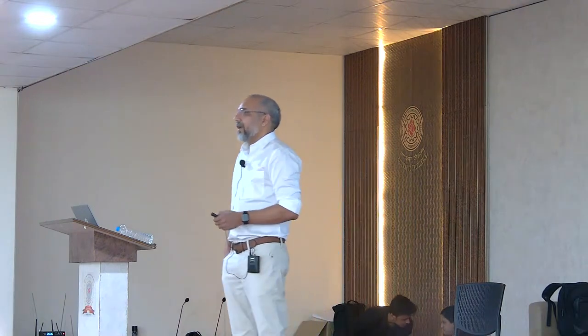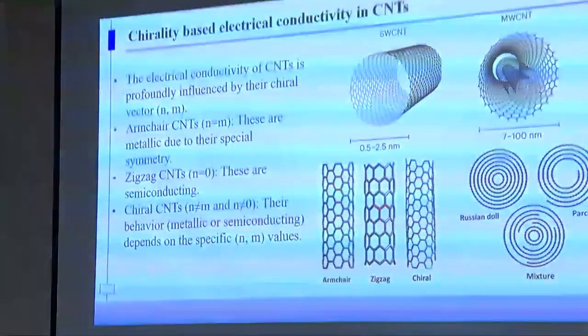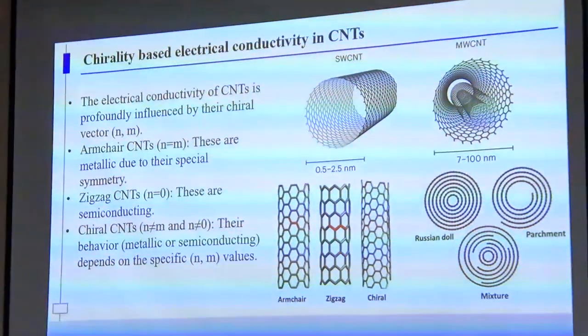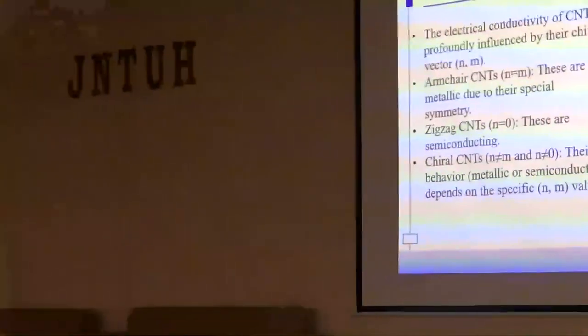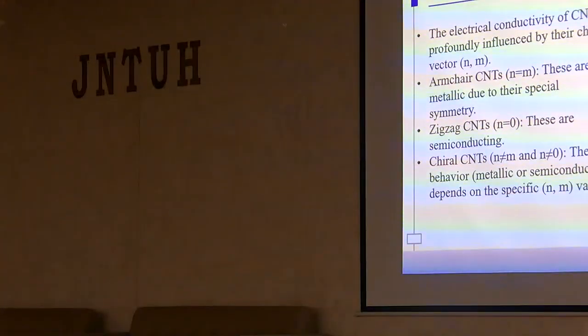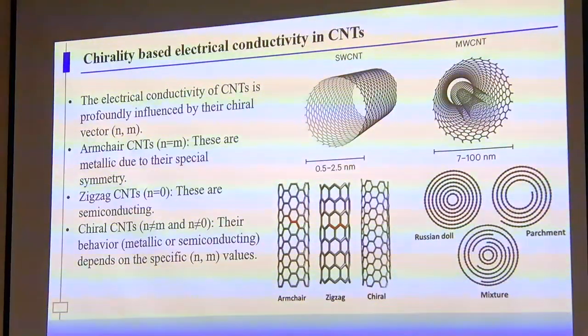So that's why, when we work with single wall carbon nanotube, we have to be very careful in terms of fabricating a quantum resistive sensor. Do you think with zigzag we can make a quantum resistive sensor? The zigzag carbon nanotube may be used for FET devices, but it may be very difficult to have a conductive network to build a quantum resistive sensor. The first condition for a quantum resistive sensor is that you must have a conductive network.